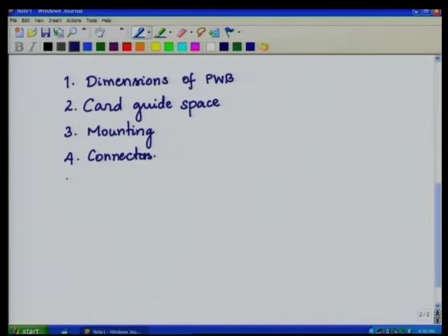Only after you have finished placing all these, you go on to the layout of the components. So, you have to lay out the components, of course, in the order of criticality. When you lay out the components, you do not have a formula for this, it is intuitive. You will learn more and more as you make more and more PCBs.